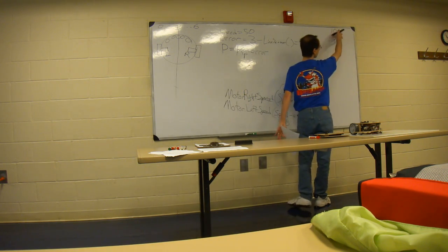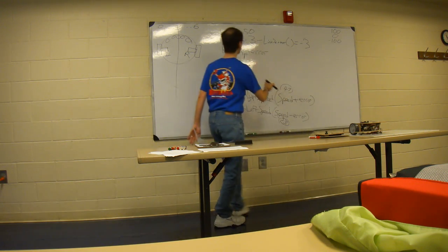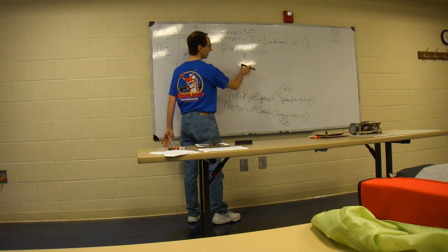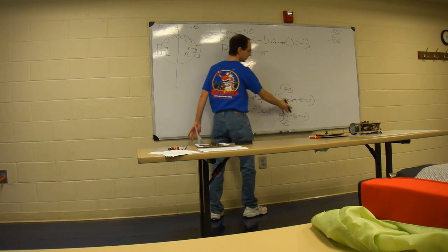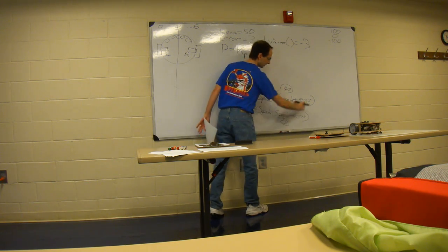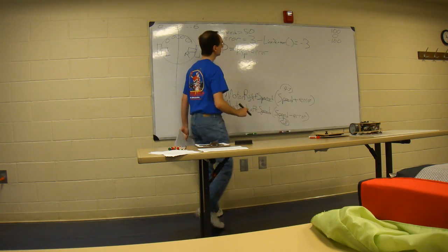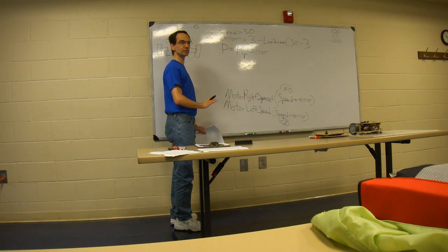If this is expecting much smaller numbers, then we could use this to turn it down. So the KP allows us to adjust how much influence the error has in biasing our speed. This error term here is a bias for the speed. Everybody understand that so far? Okay.